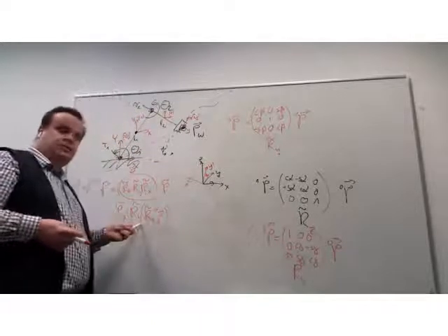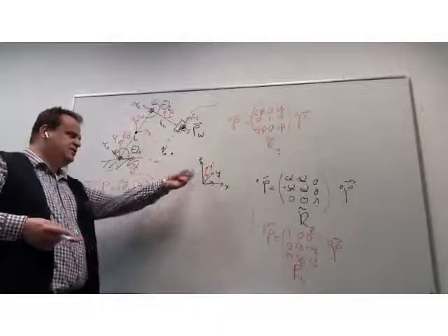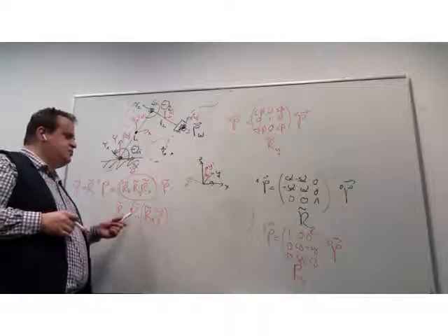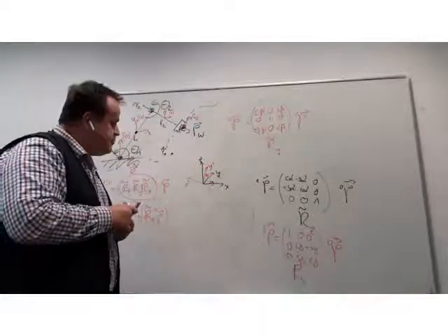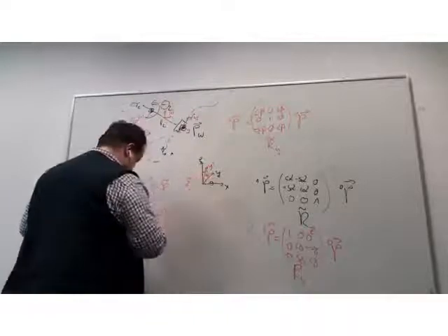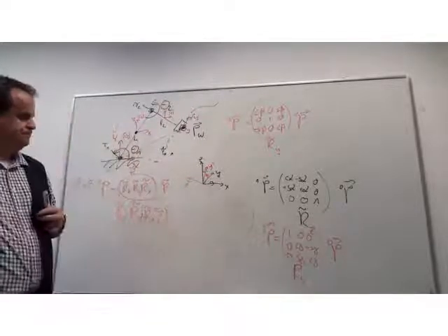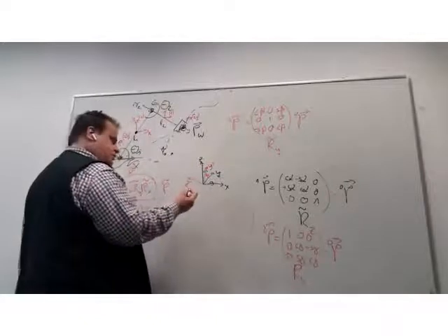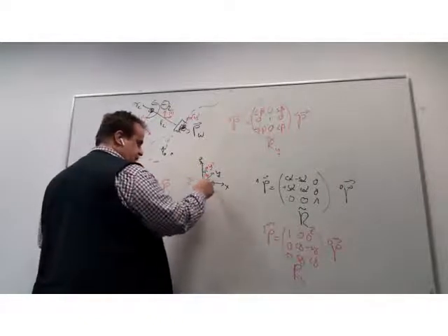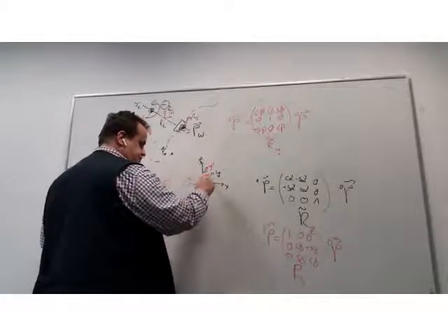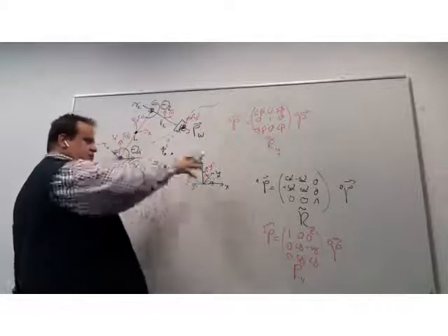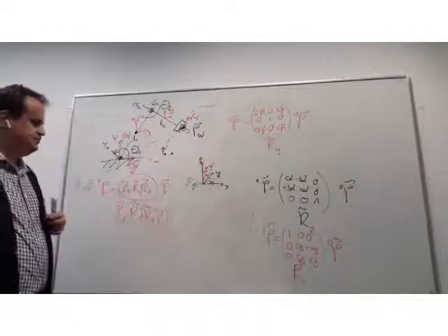Now the next y we are applying is not really the original y. You need to remember it. The y this system is rotating around is the resulting y. So I am rotating around actually this y prime. And now I rotate basically the x and the z. This will be an x2 dot and the z2 dot rotated around the corresponding y vector.